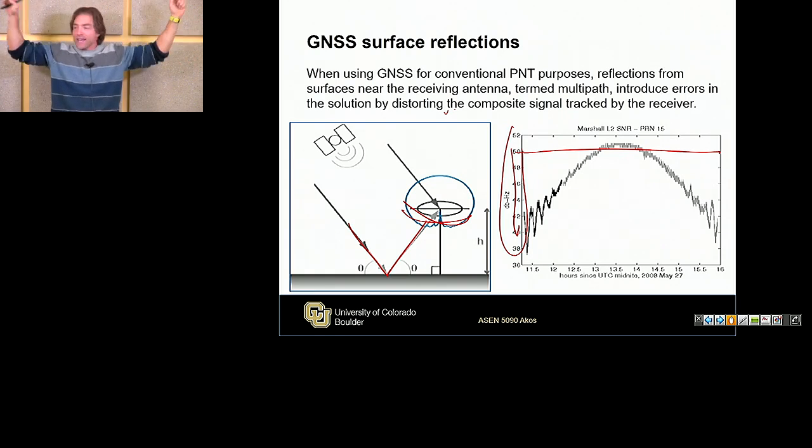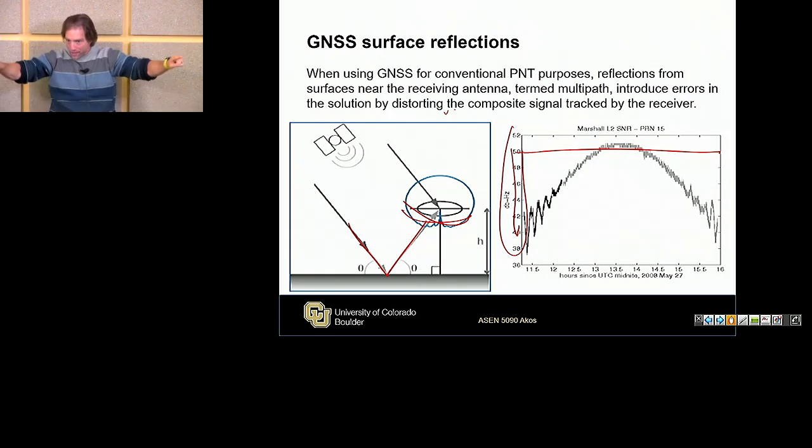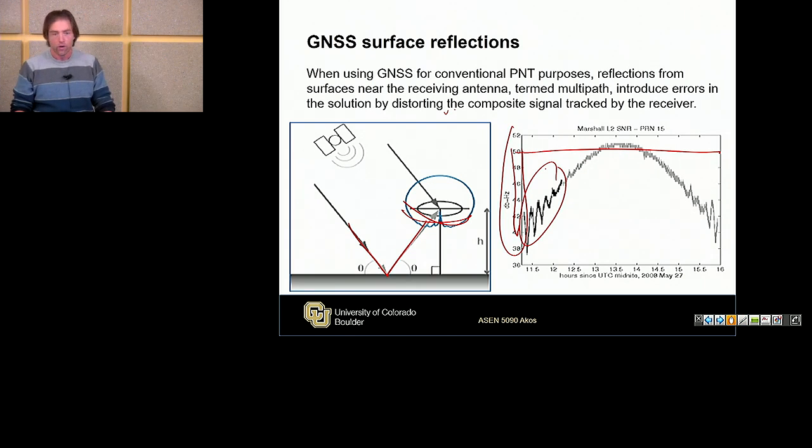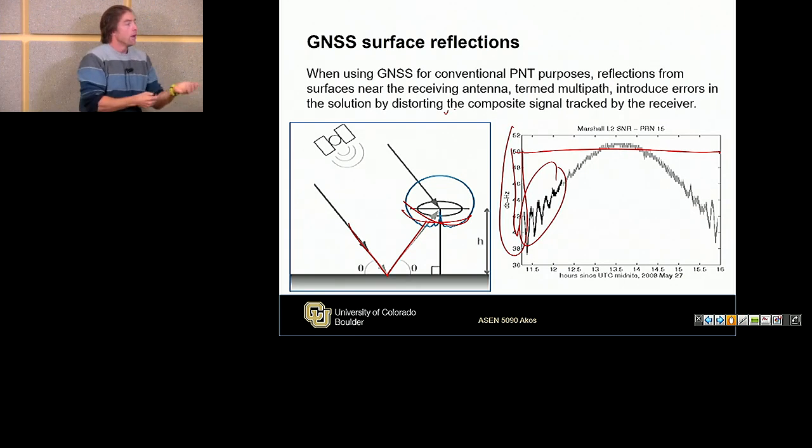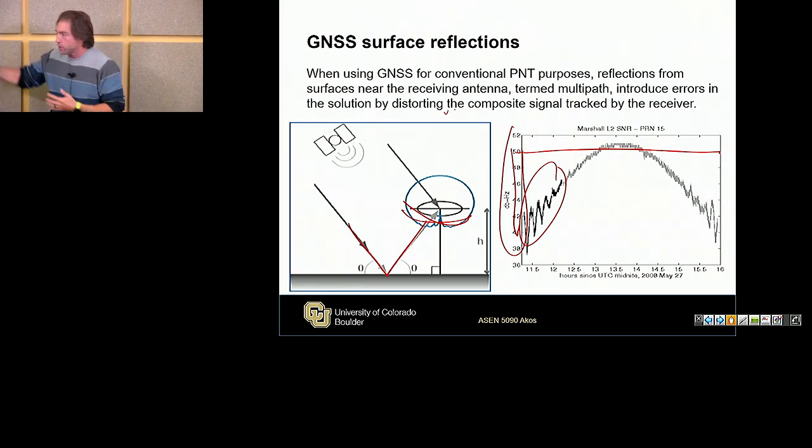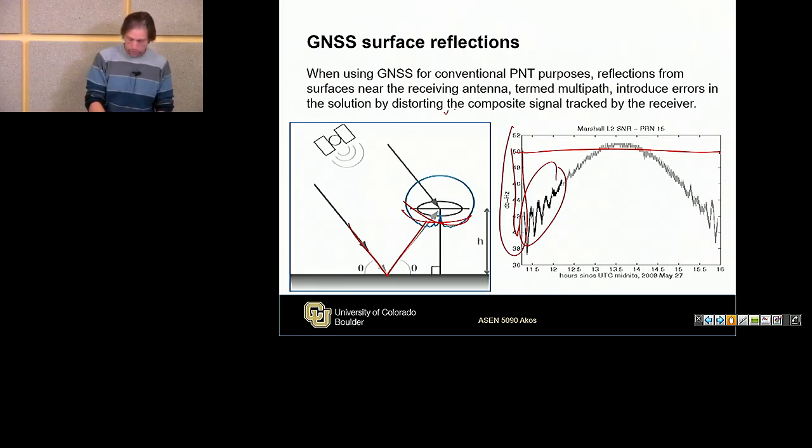I can't just make a hard cutoff right at 20 degrees. Everything's not going to be perfect, so I've got to kind of rope that in just a little bit. Most of this variation is coming from my receiver antenna pattern, where the satellite antenna pattern is trying to model that. But there are some additional attenuations, particularly as I go through the atmosphere. But most of that is coming from the receiver antenna pattern. Okay.